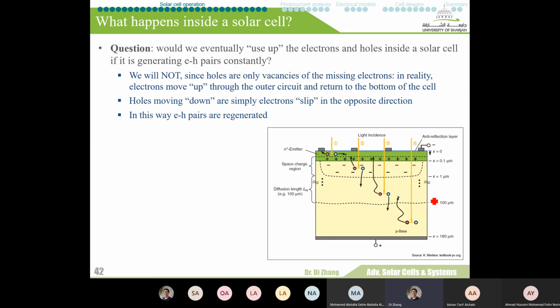This is first of all just a very quick reminder about our lecture last time. What did we talk about last time? We discussed the equations inside the PN junctions, and we further discussed what needs to be changed for these equations if we incorporate them into operational solar cells. For the equations specifically, we have to introduce several new parameters. Specifically, that is going to be the generation rate, which is related to the absorption coefficient we mentioned before, as well as the recombination rate.